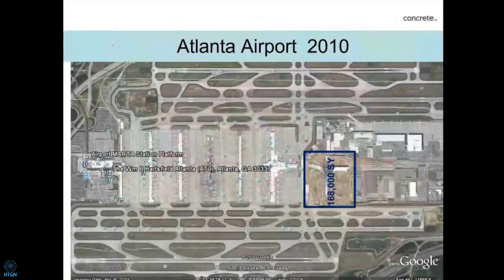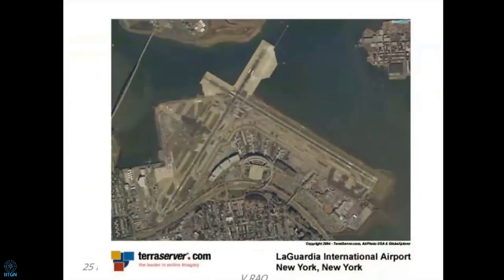Now, in this case, particularly in Atlanta, maybe the direction of the runways are all going to be in the same direction. But if you go to, let us say, the New York airport, it all depends on the conditions. In certain weather conditions, the crosswind is going to be more. I think you might have been taught the Windrose diagram also. So we should try to find out that 90% of the traffic has to be in one direction if the wind is like this.